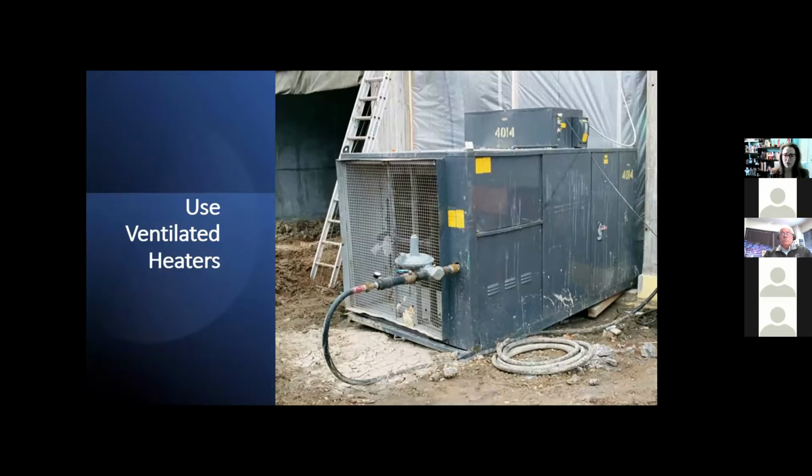I mean, this is going to cause a lot of issues as you're driving forklifts over the surface of the concrete and you're creating wear and tear on that surface. It's not an abrasion resistant concrete. If it's a basement slab, what's the final surface? What was the expectation of the owner? Were they going to put carpeting down? Then you're okay. Were they going to put tile down?